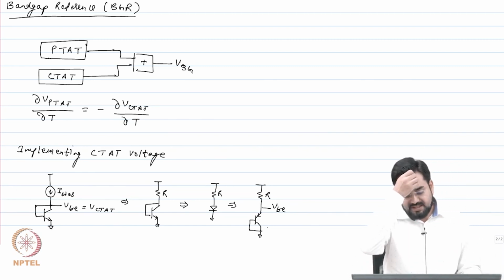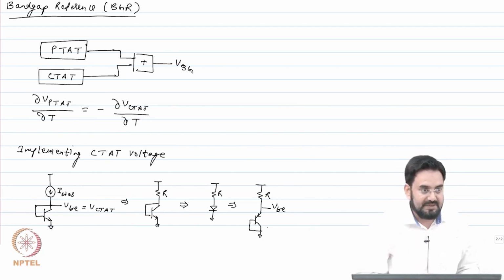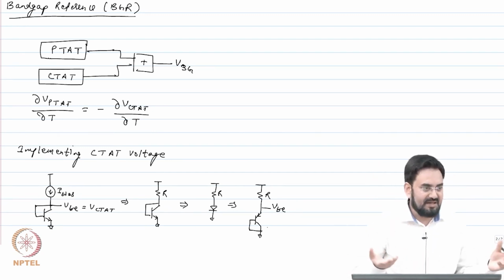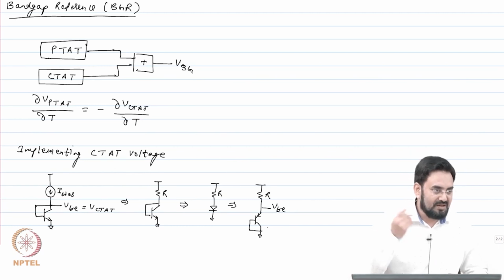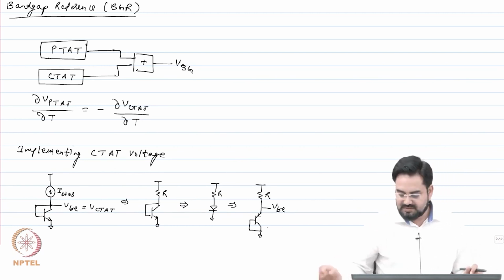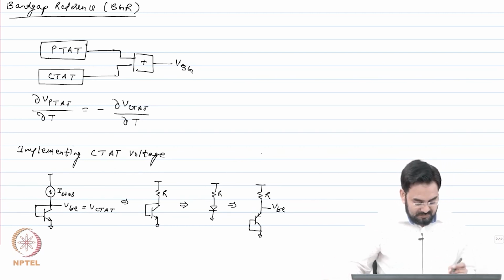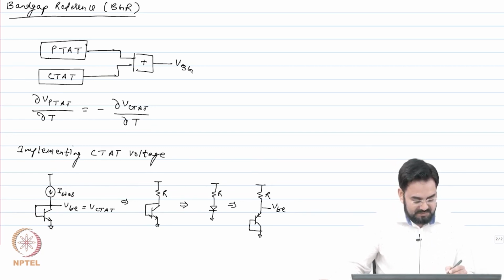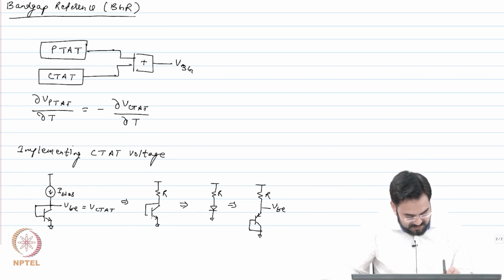Okay, so, the difference between active and parasitic is the gain, the beta of these bipolars is very bad compared to the active. Active may have more than 100 beta or so, these guys may have, I mean, much less than 10 or so. So, that is why we mostly use these substrate PNPs in order to design the bandgap for standard CMOS. But if you have a process which has an active bipolar, then you are free to use it.